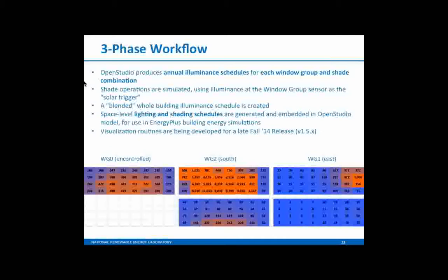And then this is the same thing for the east window. We've got some light coming in. It's not as intense because it's probably not direct like it is here, where we're seeing almost 9,000 foot candles, whereas their peak is 1,000. So maybe we're getting a little bit of direct, but it's mostly sky brightness there. And then again, the user dropped the shade here.